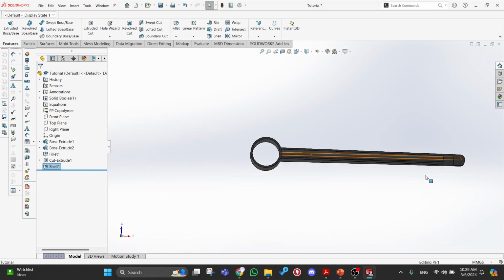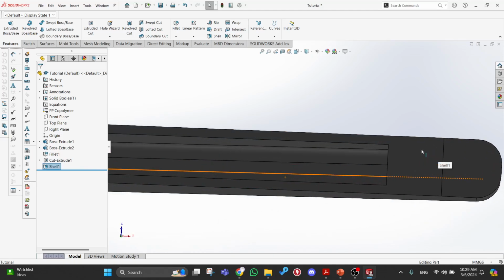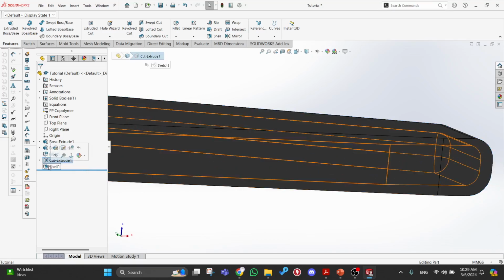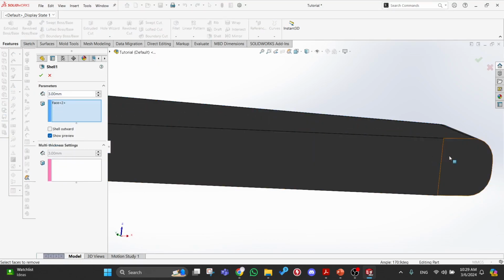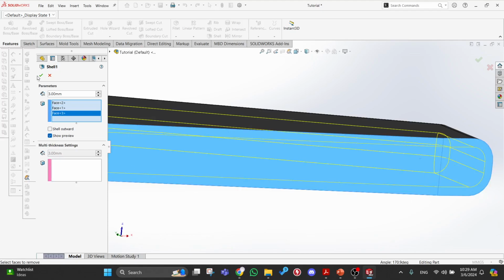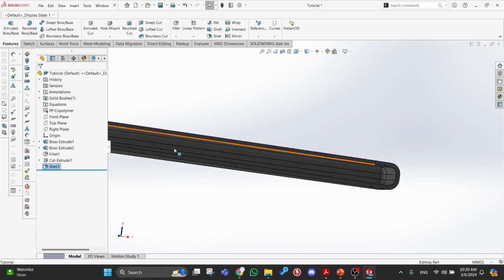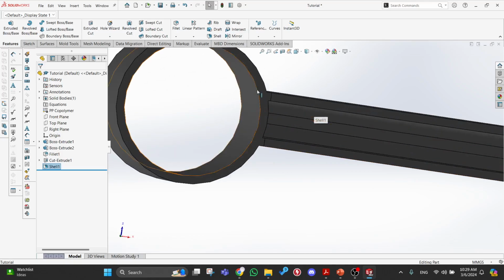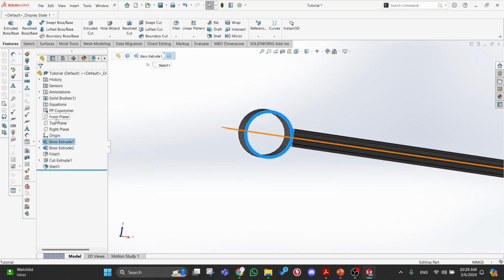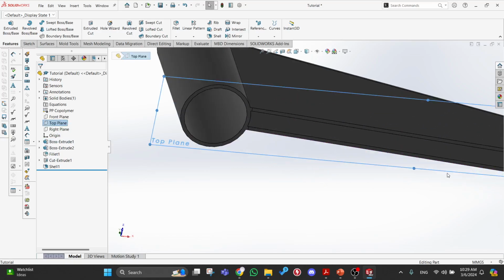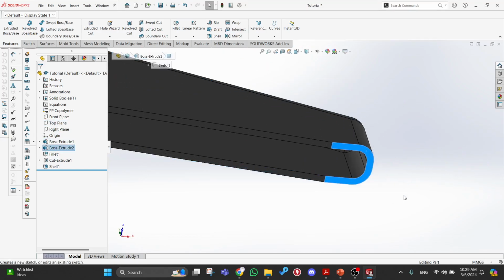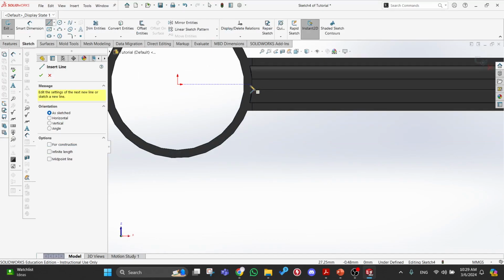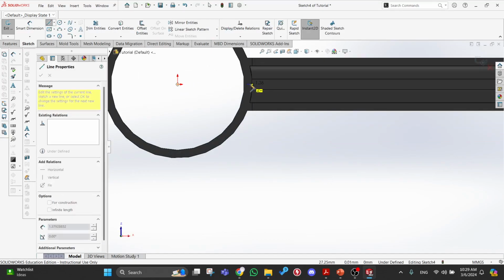let's create our, oh, I forgot to shell here. Oops, my bad. Here and here. Then, okay, now we need to create an inner rib. For our inner rib, which is just very simple, yeah, it's flat, right? So we just use this as our base, and then we'll create a rib down here.